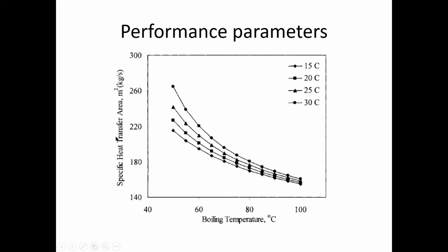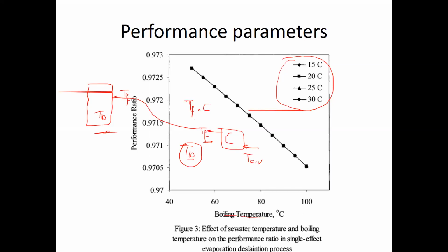Doctor, now I have some suspicion regarding the previous claim. If we increase the temperature, then the capacity of air to carry vapor will increase, right? There's no air carrying here. Remember, I said at the beginning that there is a major difference between this and the HDH. In the HDH, we depend on air to carry the vapor. Here, there's no air in the system at all. The vapor is generated, and then the vapor itself is moving from one place to the other.